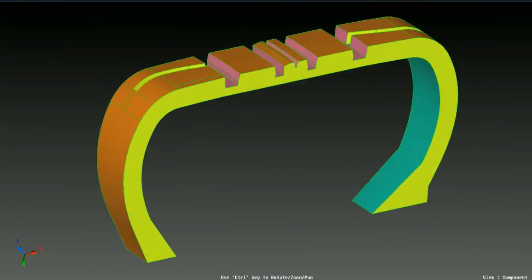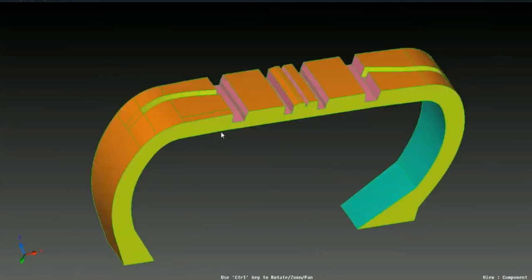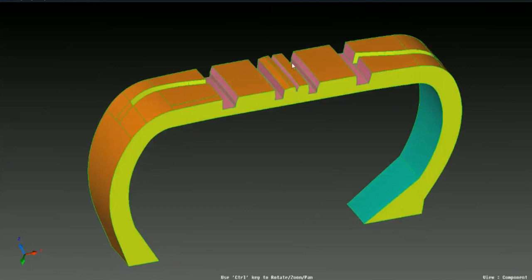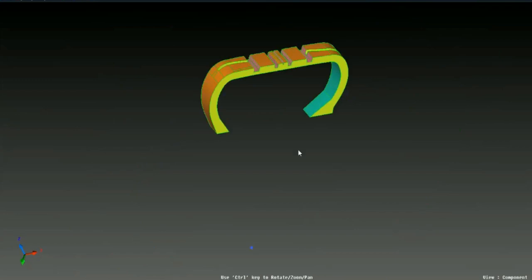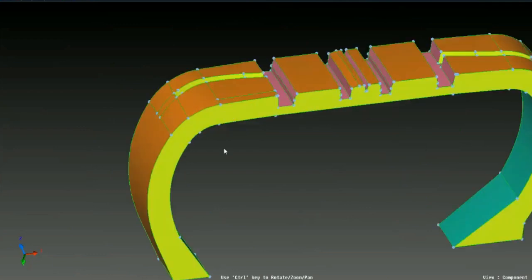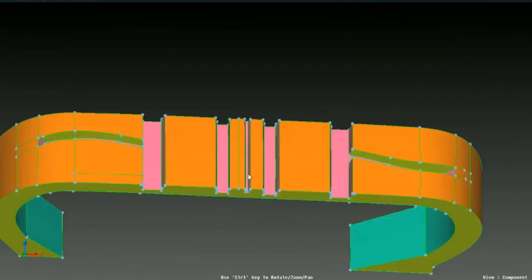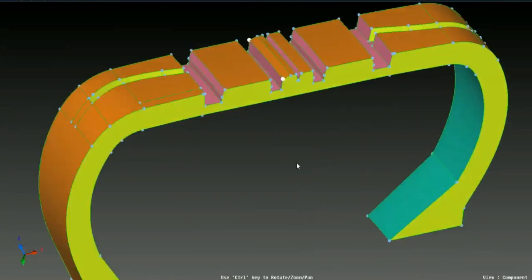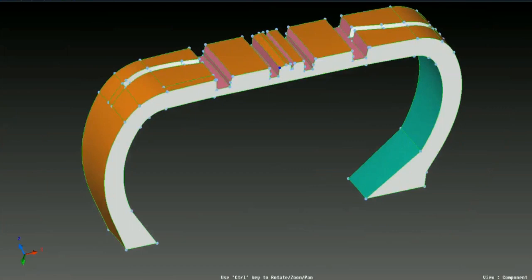Now once the CAD has been organized as per our requirement, we would like to click on single pitch hexa meshing, where we would like to create a cross-sectional surface mesh. Here the process is that we create a surface at the face and imprint all the features onto that surface so as to get nice meshing. For that, I would like to select my axis, my center point, then I have to select my width CAD points, then I'll select my extreme end points, and then the surface to imprint. This is the side face which I need to select, and simply click on create cross section.